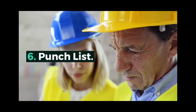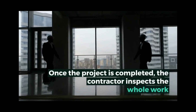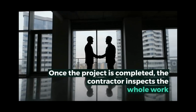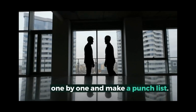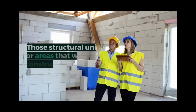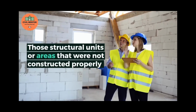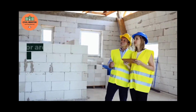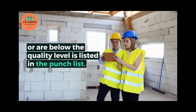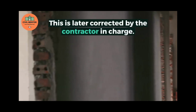6. Punch list. Once the project is completed, the contractor inspects the whole work one by one and makes a punch list. Those structural units or areas that were not constructed properly, or are below the quality level, are listed in the punch list. This is later corrected by the contractor in charge.